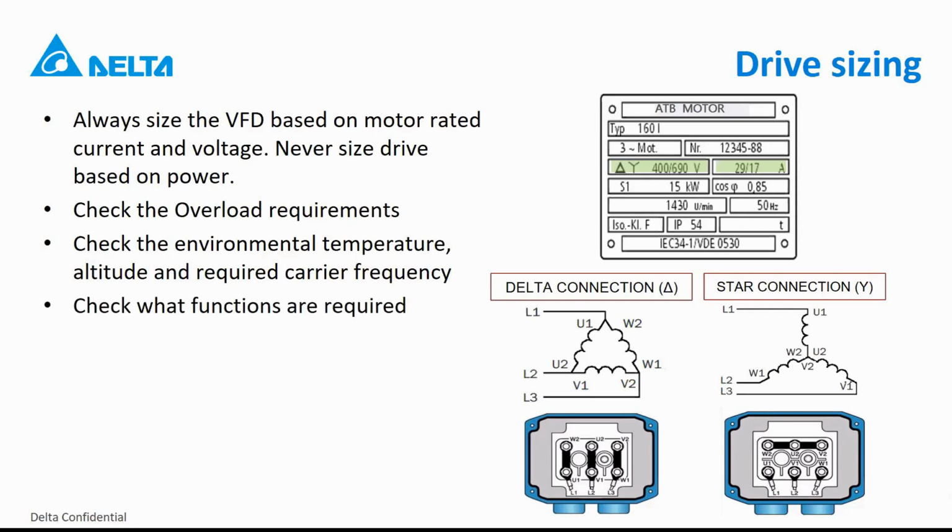So finally, we also need to check what functions are actually required. Make sure whether the application needs the drive to control some mechanical brake, or if the application needs to use different functions, you have to check the user manual to see if those functions are supported by the drive.